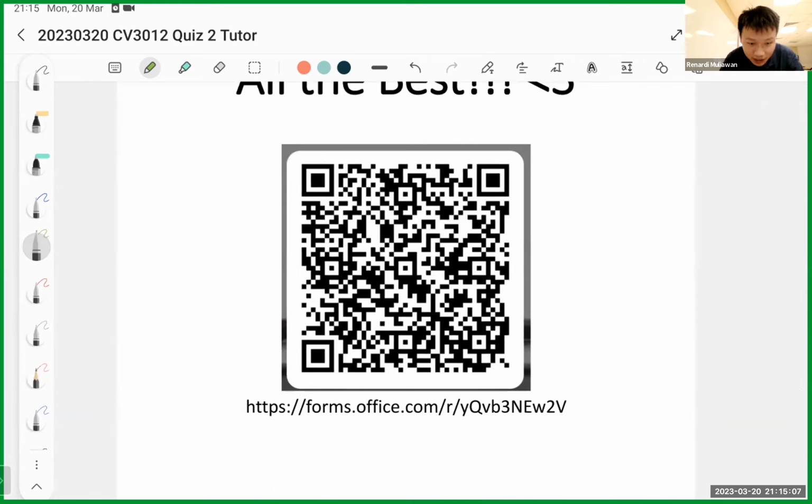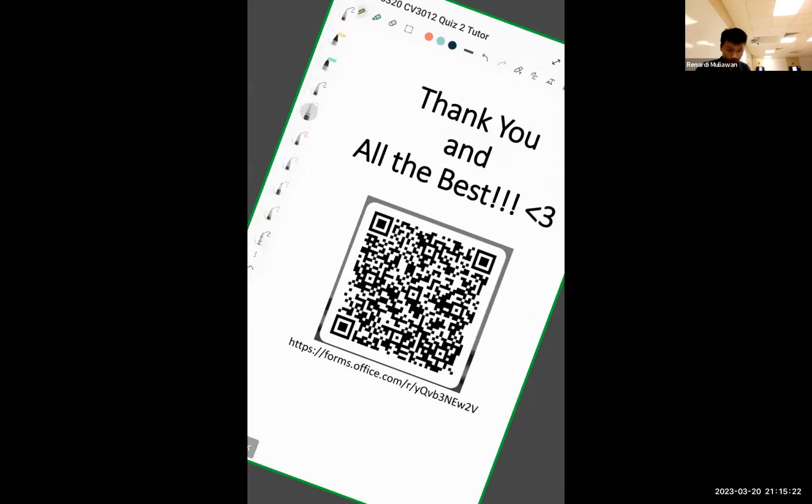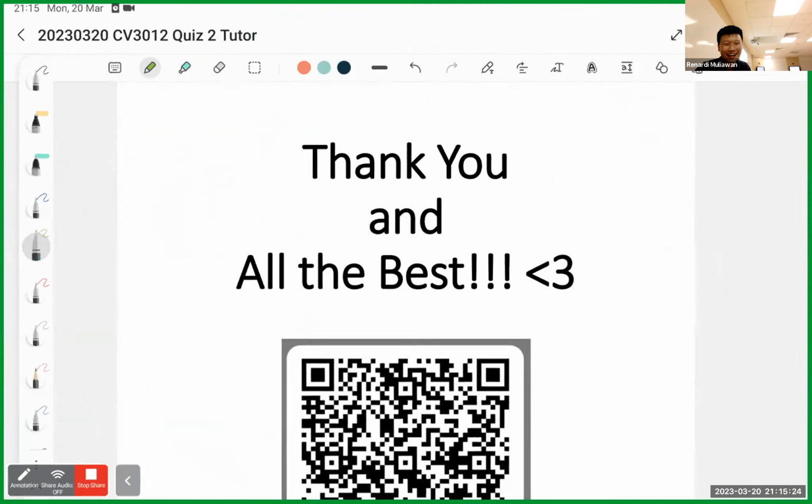Sorry, may I know when to use hot finish? It's always hot finish. In Singapore, the production is always hot finish. That's why we always use hot finish, unless stated. Then what else? Just be careful when you check from the book, because sometimes people forget to check the hot finish. They see the cold finish one. So just be careful because the properties are different, especially the W.